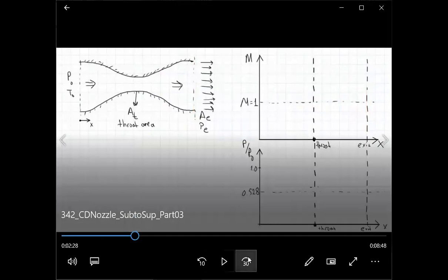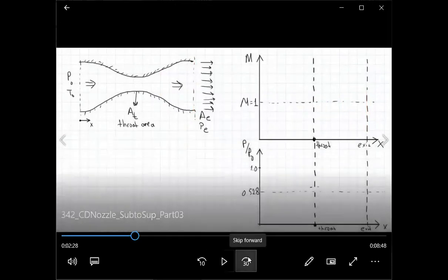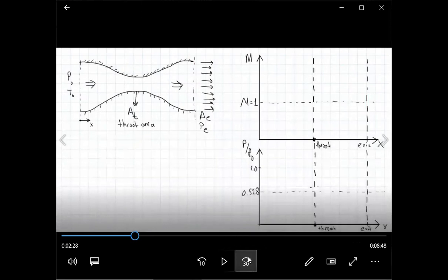Should we drop the pressure even further for higher Mach numbers? Higher Mach numbers where? Higher than condition 6. You mean if there is more drop in the exit pressure? If you want to drop the exit pressure more, it will not change.